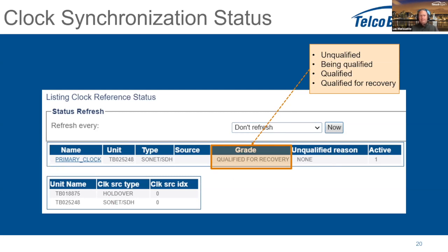On a 1+1 system, since it's one device that is master, you will see only one device with the clock source. If you see something like this all over, that means it's an internal clock of the system, where we're using a local oscillator on the device to clock the system. It's not as precise as a service provider clock, but it can certainly hold the signal. So you can still see data being sent in and out. It's just that you may have slips over time, and that in some cases will cause issues.